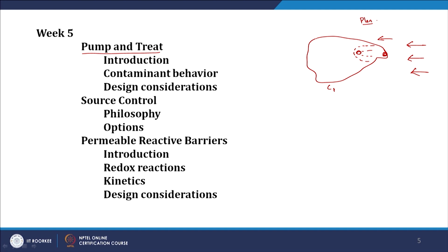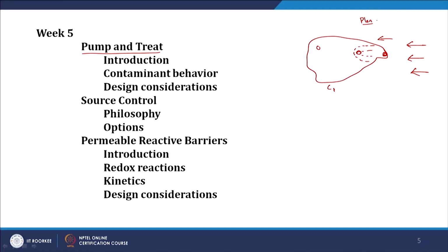So here we are going to have to come up with a scientific explanation, an explanation based on science, that would help us capture the plume. In that context we are going to look at the number of wells required, the distance between the wells required, and the distance between the top edge of the plume and the center line of the wells, and then the capture of the plume based on capture lines or flow lines.